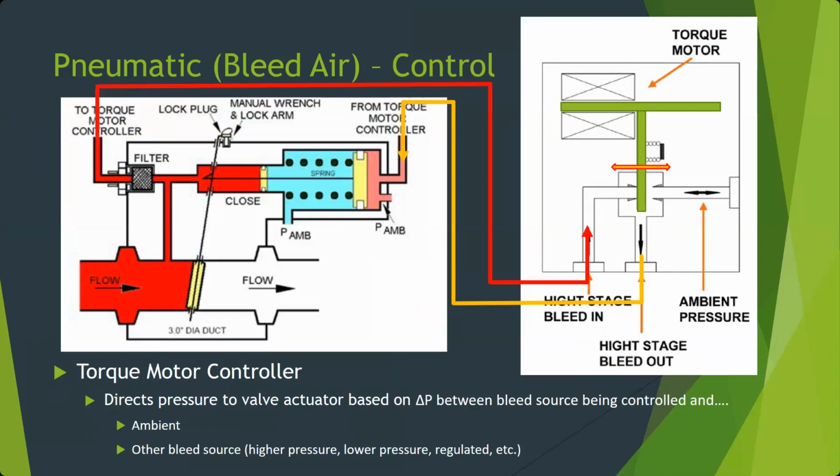So these are often used for those combo valves. It can be a shutoff valve. In this case, the spring provides your shutoff function. That's going to push the valve closed. And then the torque motor is going to adjust how much it's open to be variable in order to regulate pressure or flow.